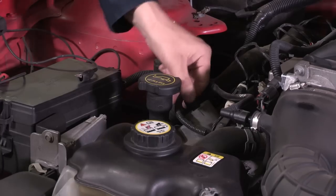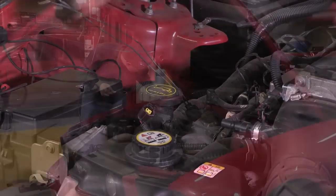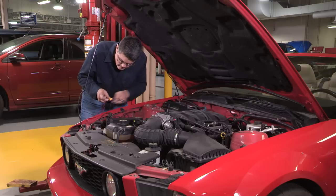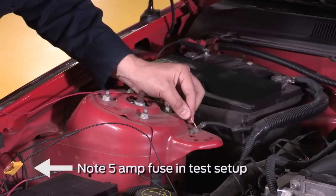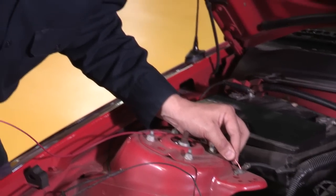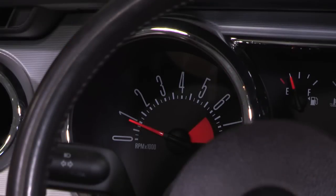A simple test to check VCT solenoid function is to provide fused power directly to the VCT solenoid. Then provide a temporary ground. Listen for an audible click from the solenoid as ground is applied. Also, monitor engine performance. If the solenoid actuates, idle quality will change.